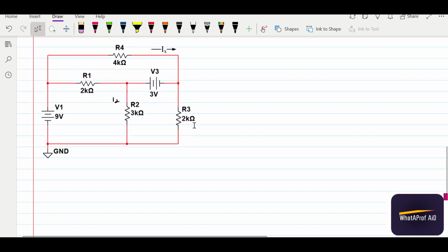And for the second case, this is actually where we have a voltage source in between two nodes. Okay, and this is considered as a single node, supernode. Then we also observe how many effective nodes this circuit has. So this only has here one node and another node. This node voltage is already known, so V1 is already known, 9 volt. And let's say we call this VA and this VB.